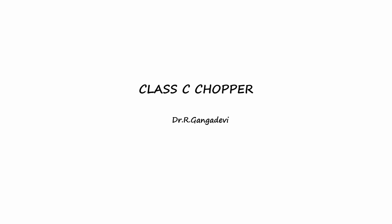Hi everyone, in this lecture we will see the operation of class C chopper. A class C chopper is a two-quadrant chopper that can operate in the first and second quadrant of the output voltage and current plane. So it is a combination of class A and class B chopper. In this type of chopper, the power can either flow from source to the load or load to the source. So it can be used as a step down or a step up chopper.